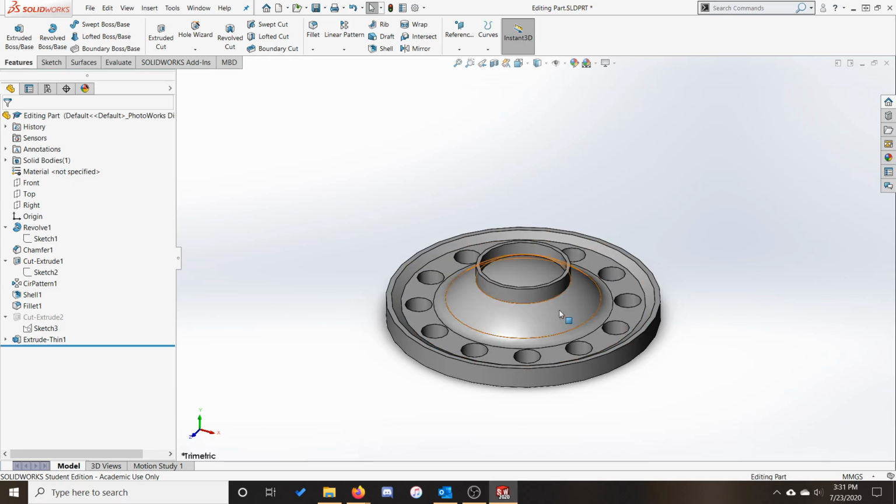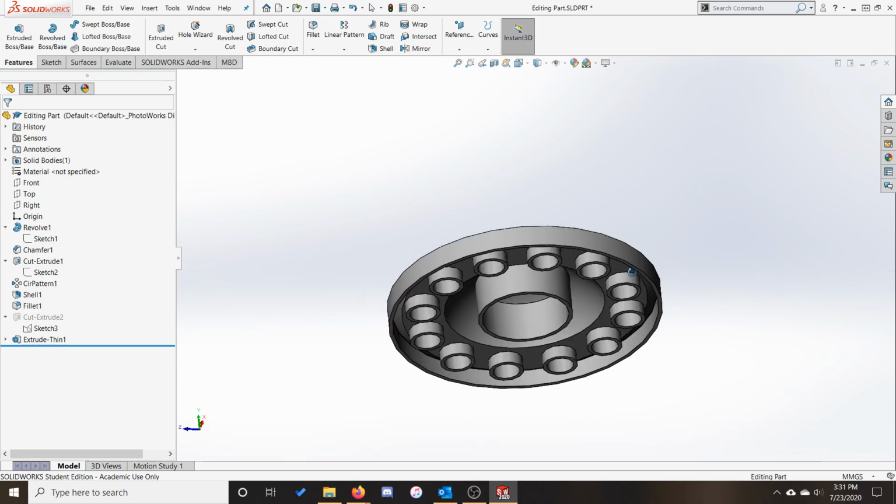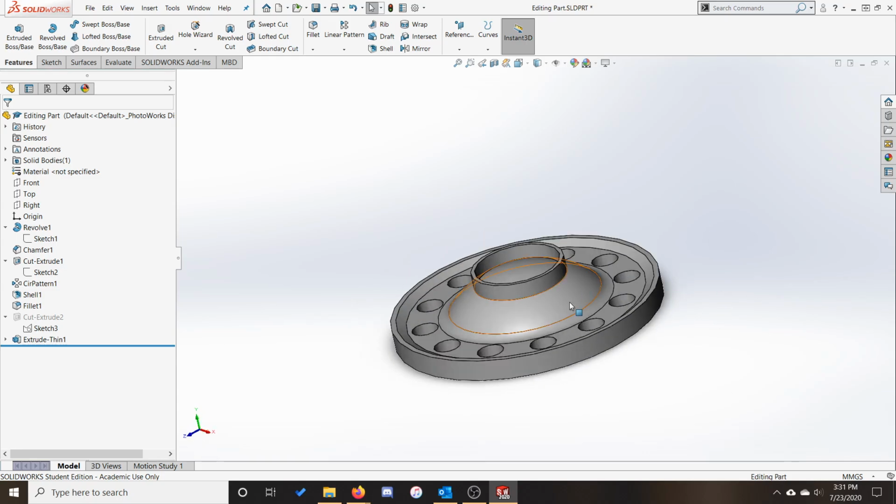Okay, what next? Let's do something about this giant tube in the middle. On the underside, it doesn't really leave a lot of room for your head to fit in, but I do like the look at the top, so let's see what we can do about it. As I'm sure many of you have already determined, you can right-click on features in the design tree and select Edit Feature to go back into the Feature's Properties menu.